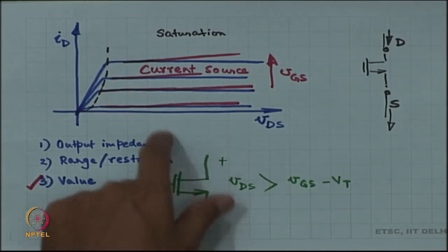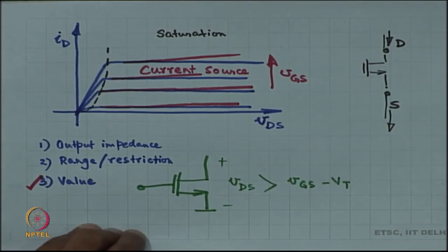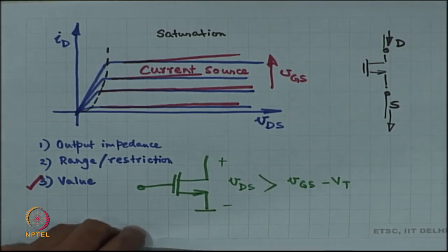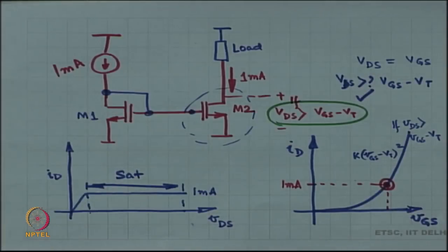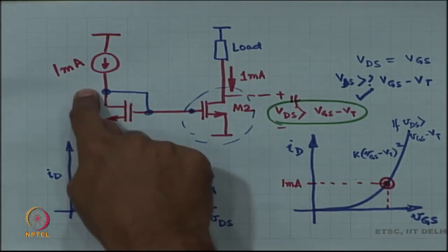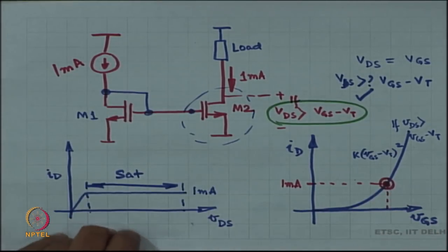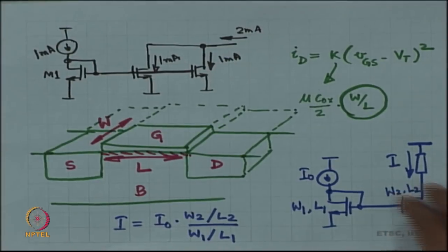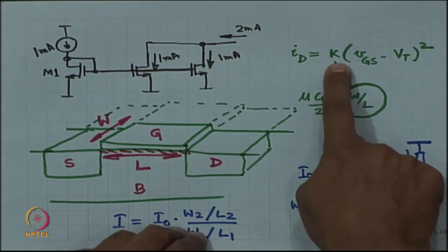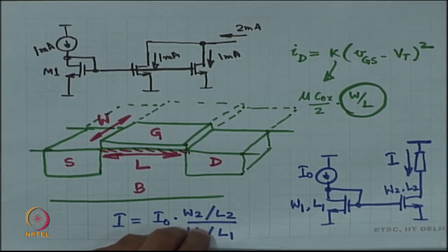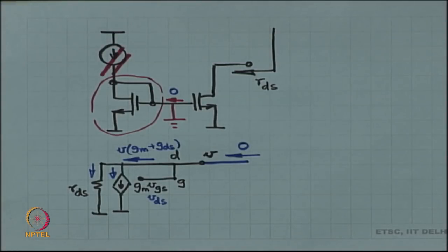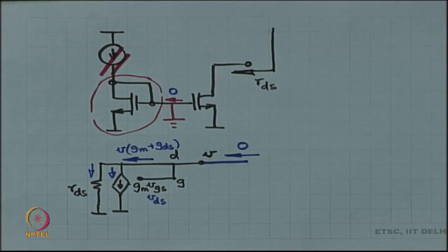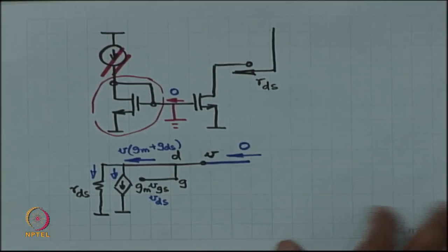Then we showed how a MOSFET is a nice current source right away, right in front of us, and then we made a current mirror with which we can generate any current if I know the value of the reference. Right? We recalibrated our MOSFET equation, right. K has been elucidated over here, and then now we are working on the output impedance. The output impedance of the current mirror is nothing but RDS. Okay, thank you.